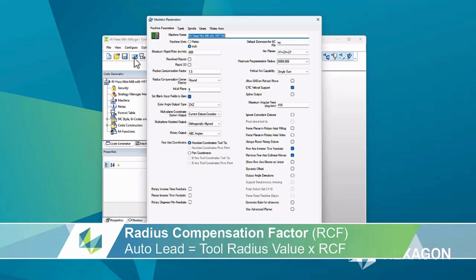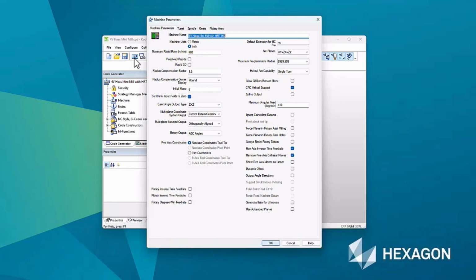This calculation ensures that auto lead moves that run onto a part to establish cutter comp are always slightly bigger than the cutter, and that will generally avoid any cutter comp alarms when running tool path generated by EDGECAM in the CNC machine.